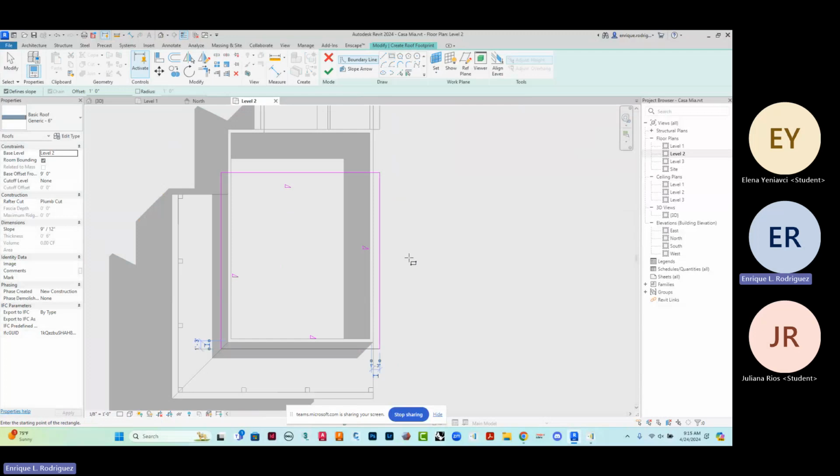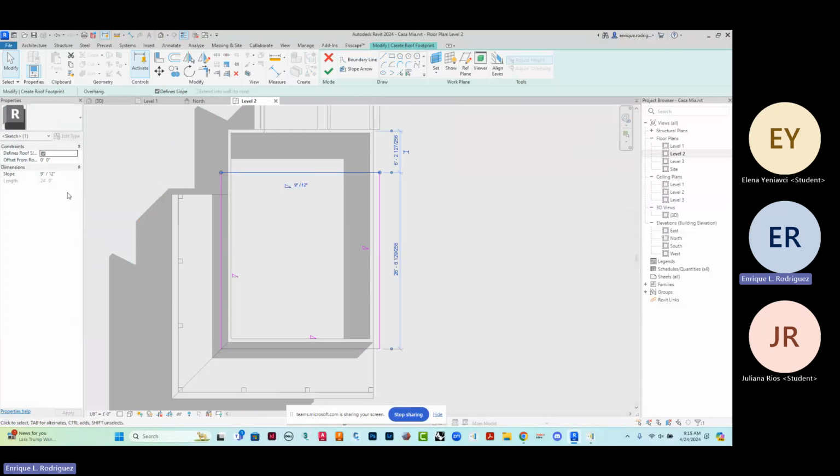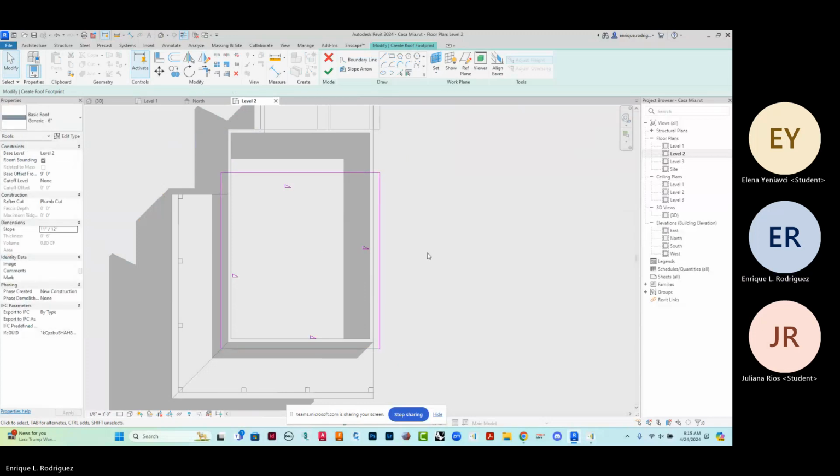Now, the second floor roof, based on the material, is a very steep roof. I'm going to go ahead and go with maybe a 10 and 12, a 12 and 12, or an 11 and 12. So let's go ahead and change our slopes. I could have done this all in one shot. I am going to highlight all of them and change that to 11 and 12. Let's see if that's stuck. That looks good.